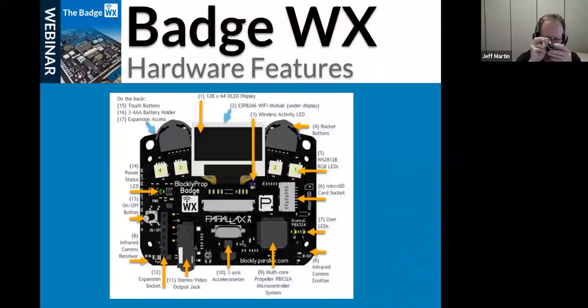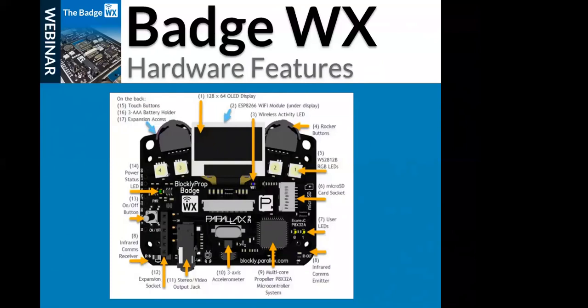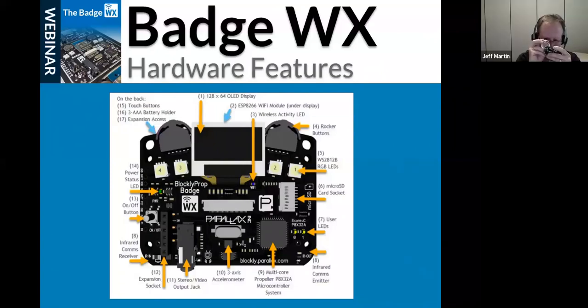There's also access to the 3.3 volt regulated supply and also the direct battery connection. P27, did you get that one? There's 3 I/O pins brought out in addition to the RGB connection, which is actually also just an I/O pin essentially, but it's connected to the signal line of the RGBs.